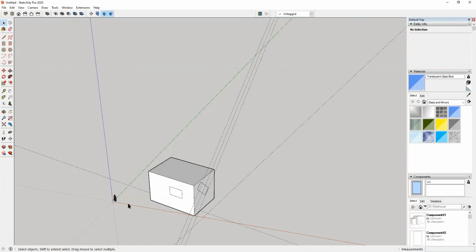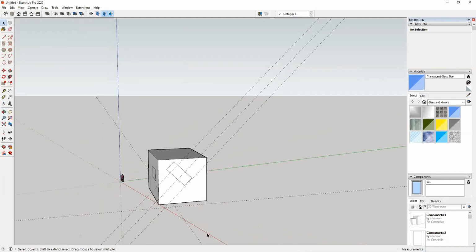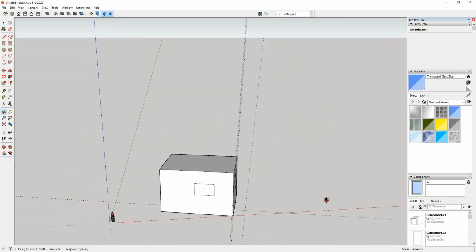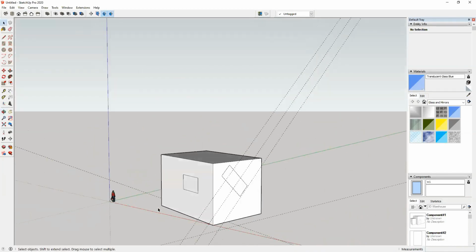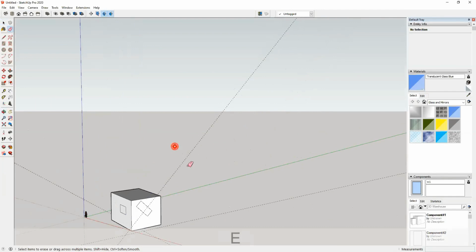In case you download an object from a library, and you see that it is not oriented properly, make sure you right click on one of the axes and see whether you are able to reset it or not. If the reset is grayed out, it means that the origin is properly located at the very origin of the SketchUp file. So you can change the axis even on a vertical face, but make sure you reset it as soon as you are done with it. Otherwise, you may get some unwanted results.